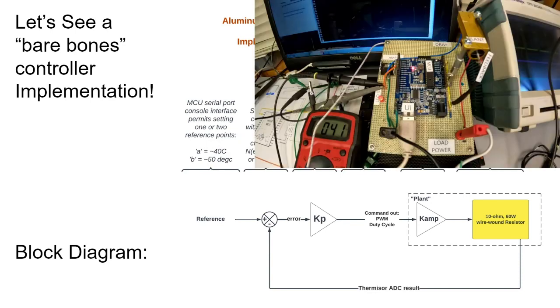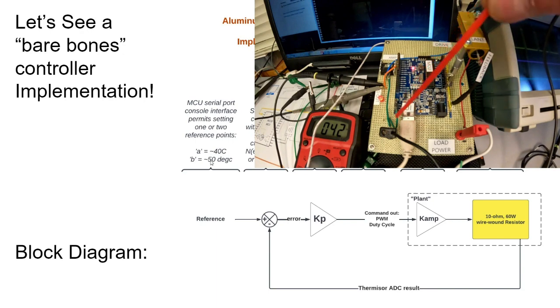And that's we can set another set point. So I have an A and a B option. One regulates to nominally 40 degrees C, the other one to 50. And if I type B, I have a console coming in, a console on the computer screen back here. You can barely see it in the video. And that's coming in on this USB port. So the microcontroller is also monitoring traffic, command traffic on this user interface, another element of near every system.